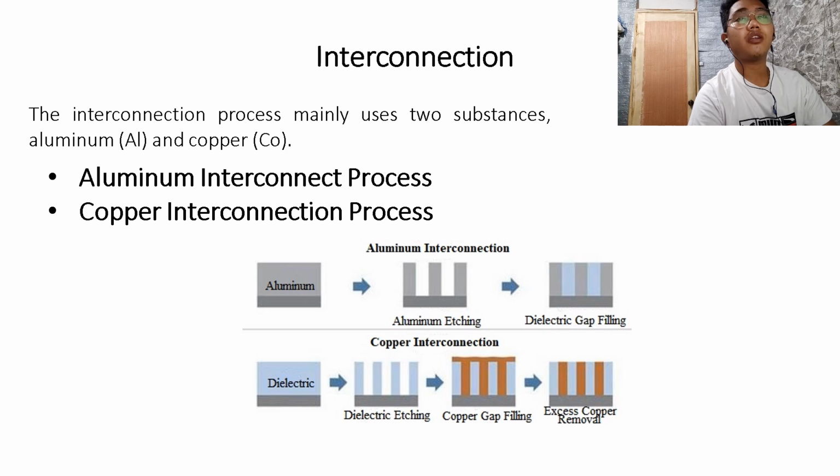And also, in order to prevent the reaction of aluminum and silicon from causing connection problems, it is also necessary to add a metal deposit to separate the aluminum from the wafer, which is called barrier metal. So, aluminum circuits are formed by deposition. After the wafer enters the vacuum state, the thin film formed by aluminum particles will adhere to the wafer. This process is called vapor deposition.